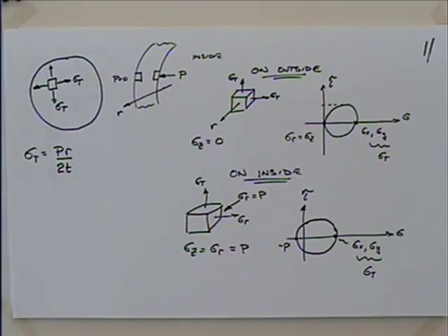You can get some pretty heavy duty pressure vessels up into hundreds of thousands of psi. A lot of interesting work in this area. Questions with that, whether you're looking at an element on the inside or on the outside? You get the larger stresses on the inside because you have the pressure there.